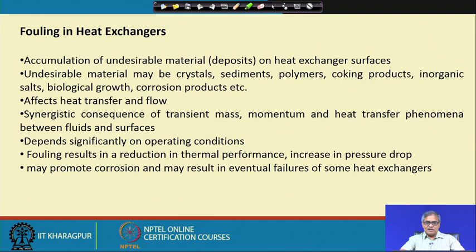That means, passages are so choked due to this deposition that almost no fluid is passing through, or the pump or the prime mover which is there in the system for circulating the fluid is unable to circulate the fluid due to very large resistance in the heat exchanger. So, this may happen.